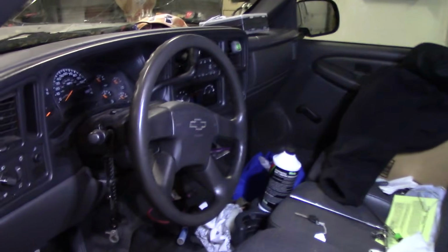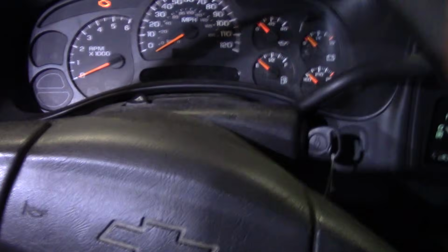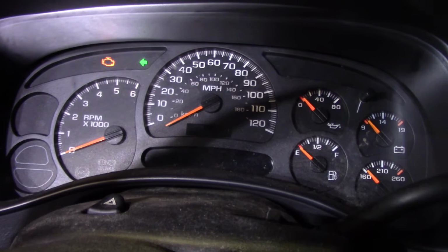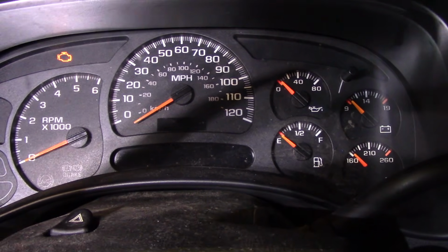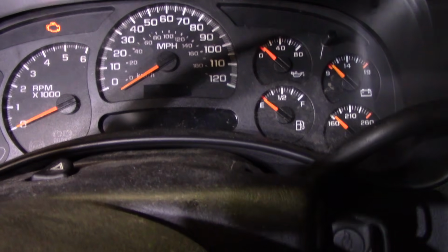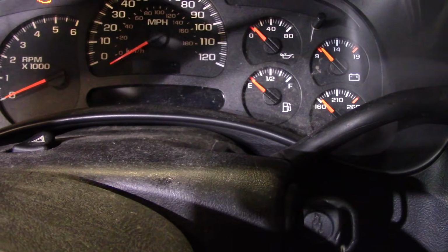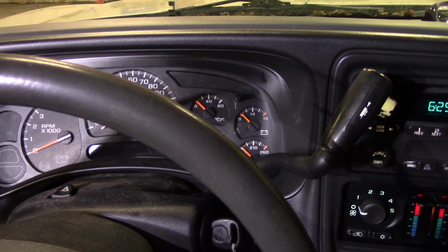So I got a few diagnostic steps for you. We'll run this thing down, figure out what's going on. All right, we'll take a quick peek here, show you what's up. Key on, and all we get is the check engine light illuminated. Like I said, turn signals function, dash illumination works, changes with the rheostat, but no gauge function, no message center, no mileage displayed or anything like that.